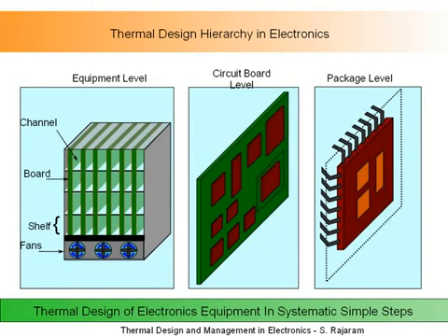We go from system to board to package, and then what we are trying to do is look at the transistor temperature, which is the junction temperature, inside this device, inside this junction, and that must be below 125 or 150. That's the procedure that we follow. Okay?